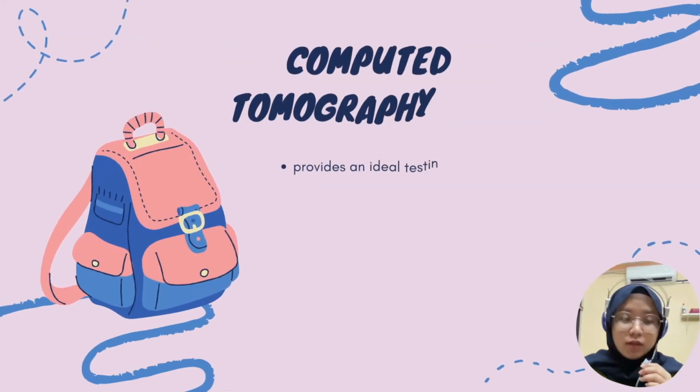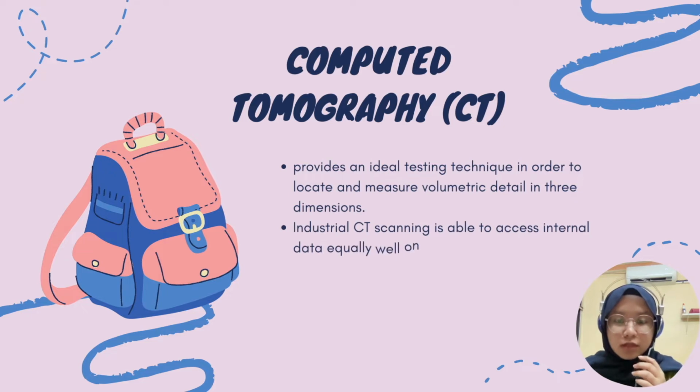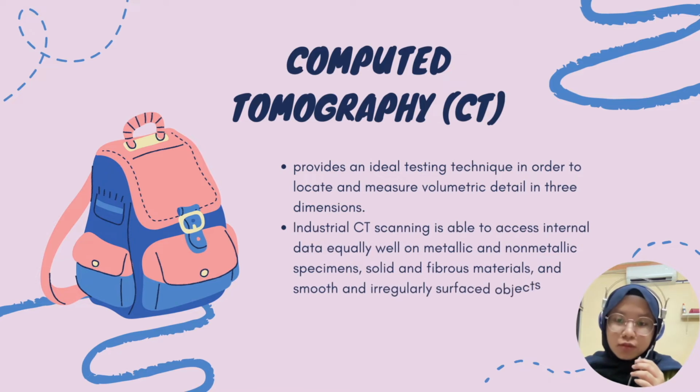So computed tomography, or CT scanning, is based on radiographic technology, which provides an ideal testing technique to locate and measure volumetric detail in 3D. The ability of X-rays to penetrate through varying densities allows the CT inspection results to provide a non-destructive physical characterization of the internal features and structures of a part or component. So industrial CT scanning is able to access internal data equally well on metallic or non-metallic specimens, solid and fibrous materials, and also smooth and irregularly surfaced objects.